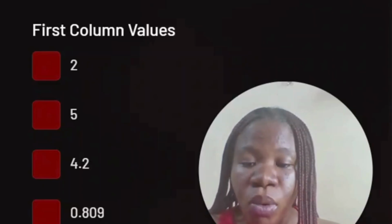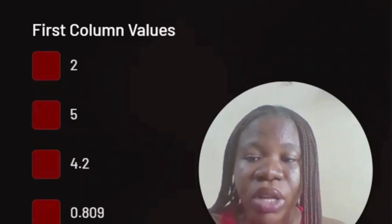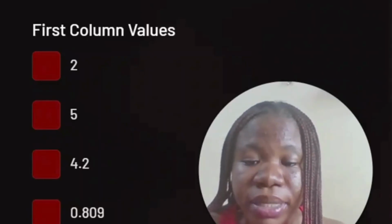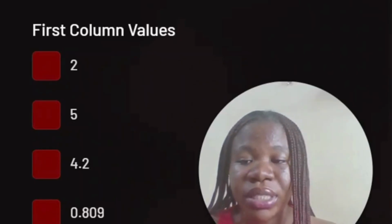So if there are no poles, or all the poles lie in the left half, it means that our system will be able to withstand whatever disturbance or inputs come. They will naturally decay over time. So now we can confidently say, as there are no sign changes in our first column of values, that our system is stable. To better understand this concept, in the next section, we will dissect a hypothetical situation to get a better grasp of it.